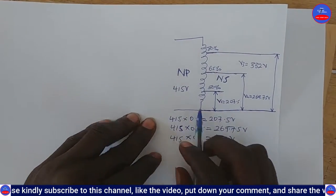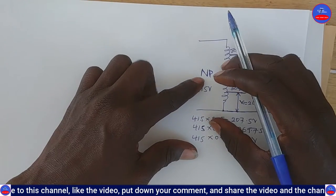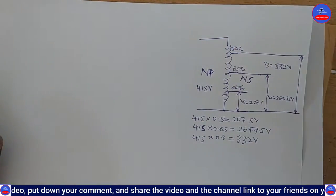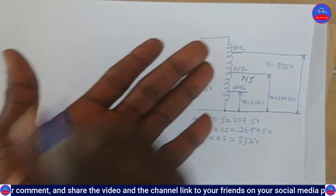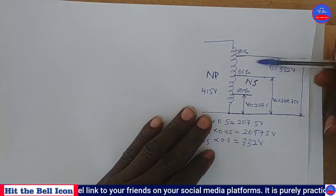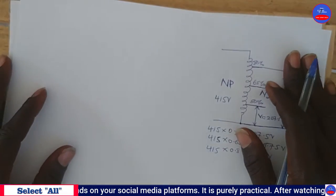The reason is that we applied 415 to the primary winding, but we are getting this side to be common. Why? Because on an autotransformer the secondary side has a start point, and all start points are neutral, zero potential. So we are going to use this same scenario to design the autotransformer power diagram.